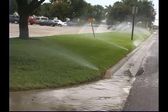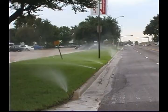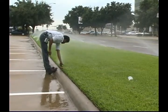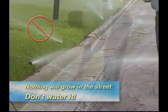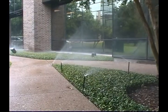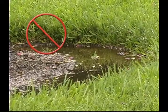Avoid overwatering to prevent excess runoff. Avoid runoff by adjusting the watering time, as well as the direction and volume of the spray heads. Nothing will grow in the street, so don't water it. Be sure to check the soil moisture and water only when the top 4 to 5 inches of soil is dry.